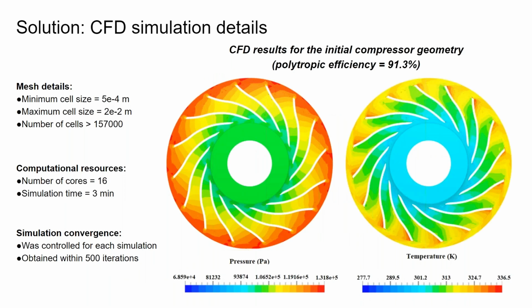The model was executed and solved with SimScale in the cloud, and we used 16 cores in SimScale to simulate this case, which led us to 3 minutes of simulation time. Numerical convergence was controlled and obtained for each simulation within 500 iterations.